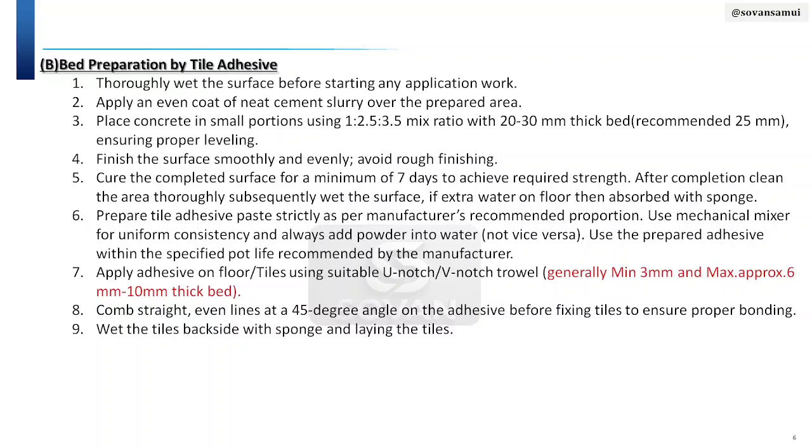cement slurry coat. Then prepare the adhesive paste strictly as per the manufacturer's recommended proportion. Means whatever manufacturer we are using for laying tiles, the manufacturer's recommended proportion of water powder ratio should be used. And ensure the mixing procedure should be a mechanical mixer with uniform consistency, and always add powder into water, not vice versa.